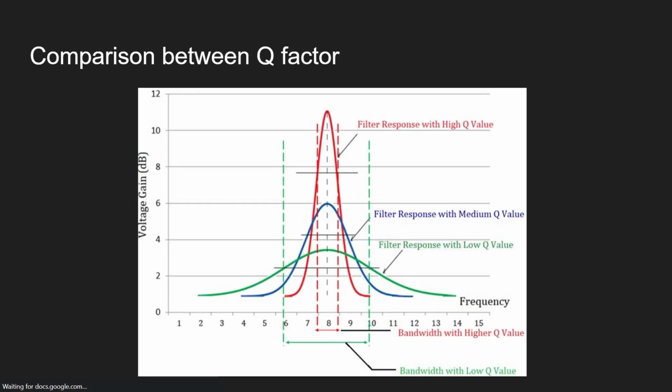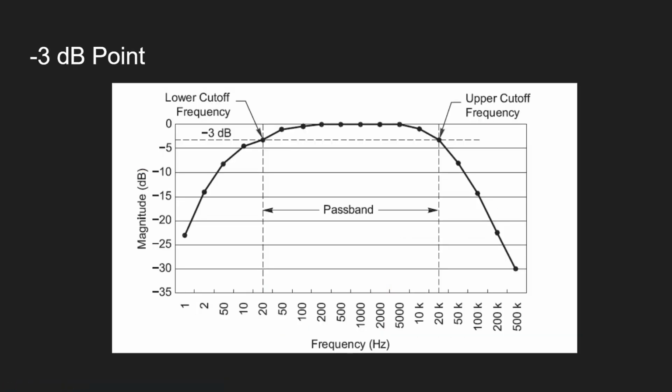Yeah. We have talked about Q factor. Q factor is the measurement of selectivity from lower 3 dB to upper 3 dB. The narrower the range, the higher the selectivity is. They will select just a small proportion. The lower the Q value, they will accept a wider frequency range. But sometimes a wide frequency range may not be suitable, we will select from case to case. Wider or narrower doesn't mean that it is better or worse.